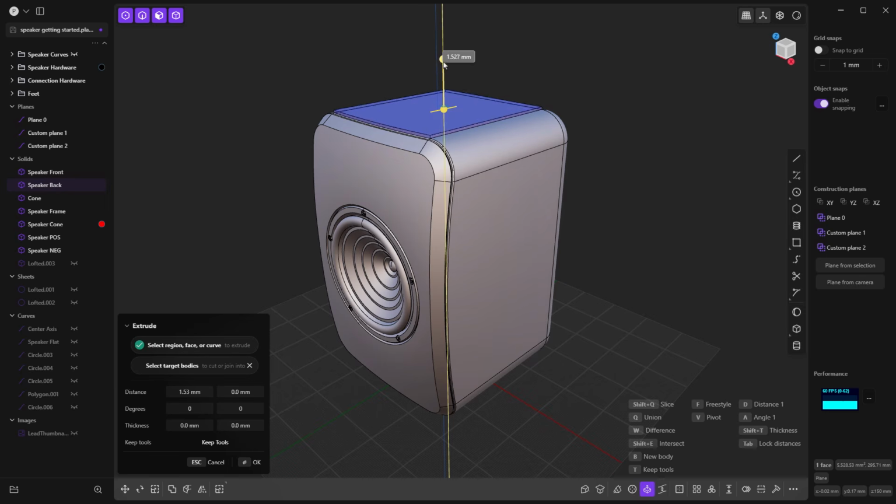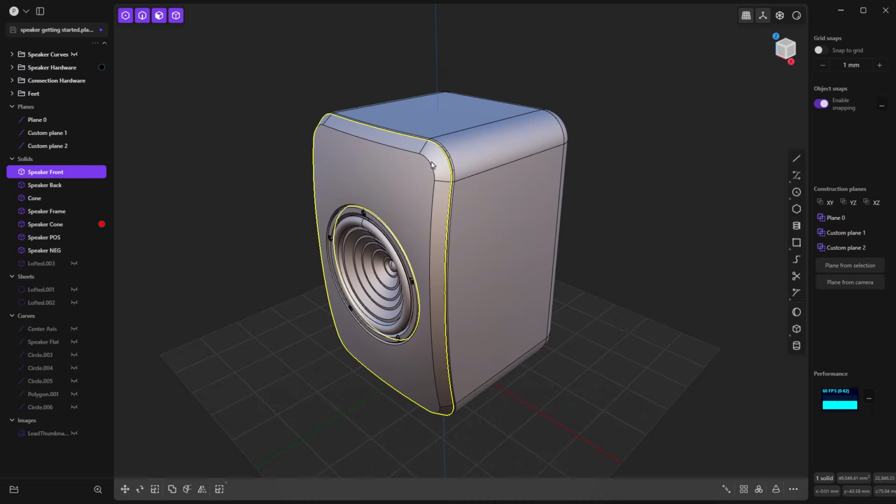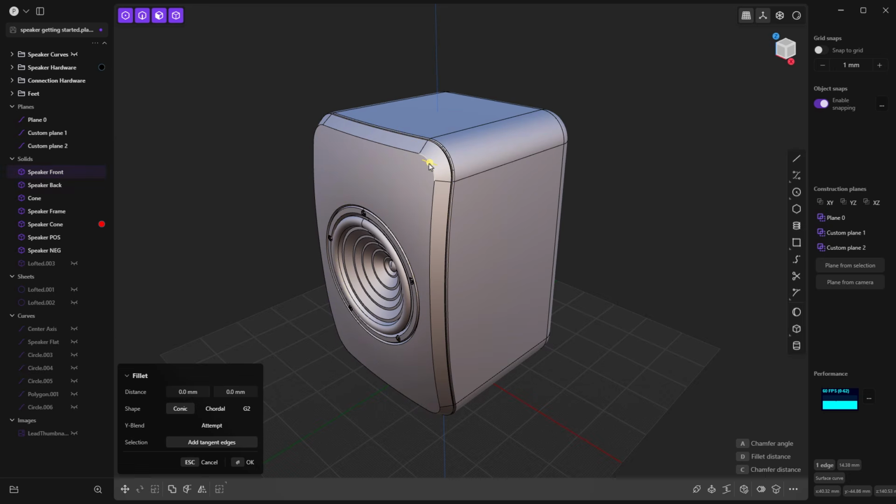In this case, I could extrude it. And extrude is different than pull because it's going to take that face and move it up in 3D. And it doesn't really care about the tangency or the curvature of the corner. It's just adding this new geometry. So keep that in mind that with these kinds of tools, there are these contextual tools that you can get access to.